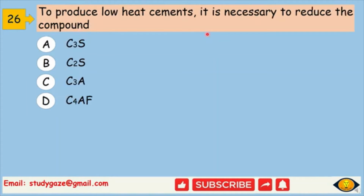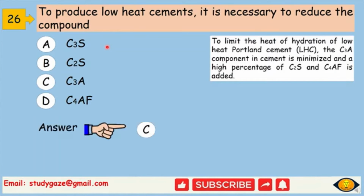26. To produce low heat cement, it is necessary to reduce the compound C3S, C2S, C3A, C4AF. The answer will be C, C3A. To limit the heat of hydration of low heat Portland cement, the C3A component in cement is minimized and a high percentage of C2S and C4AF is added.